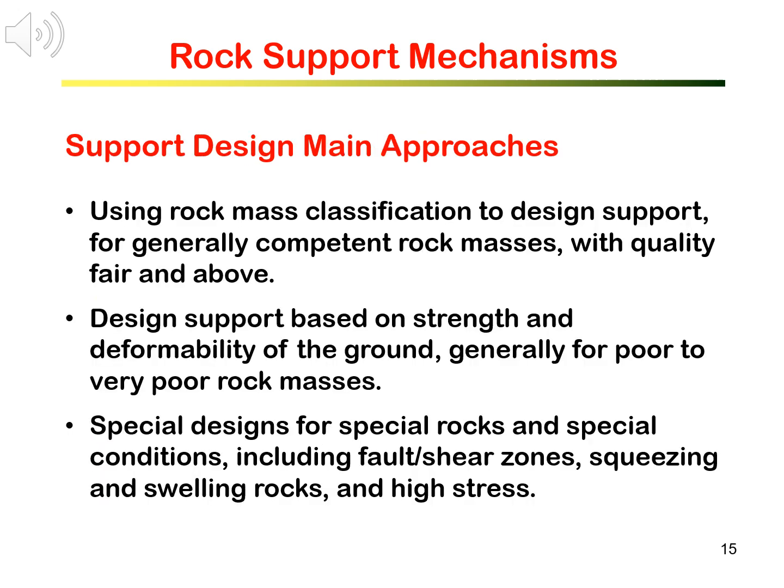There are different approaches to design rock support for underground excavations. The main approaches are summarized here. Perhaps the most popular approach is to use the rock mass classification systems to design support. This approach is perhaps most suitable for generally competent rock masses with quality fair and above.